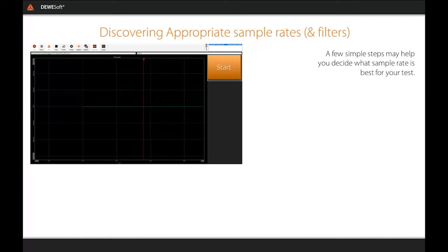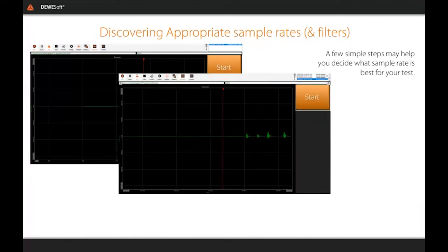In this series, I'm going to start with static data. In essence, the test object completely untouched and unaffected by anything other than the natural surroundings. Now, you could even do this with the excitation turned off. That way you even remove possible effects from the power coming from the measurement system or possible ground loops. And you may want to do this just to become familiar with what does happen when you electrically excite your sensors or not. In step 2, I'm going to use a hammer or some other mechanism to provide a sort of controlled wave through my test specimen.